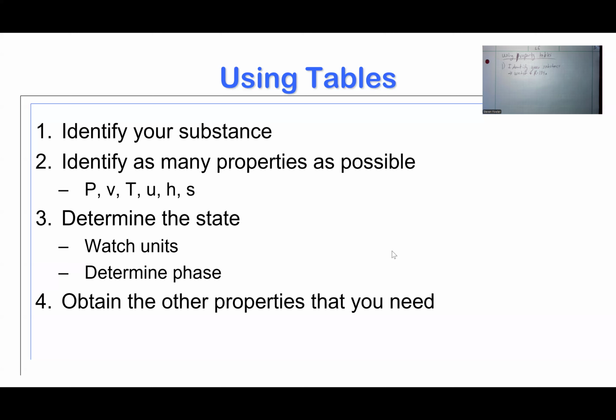But your textbook just gives you property tables for two substances, and the mentality there is if we can teach you how to use it for two substances, the saturation tables for any other substance work the exact same way. So if you did have ammonia or propane, you could pull a similar set of property tables from another source and figure out what properties you needed to size or estimate energy use or how large of a compressor you needed, etc. So we just have water and R134. The way we use these tables works the same for other substances as well.